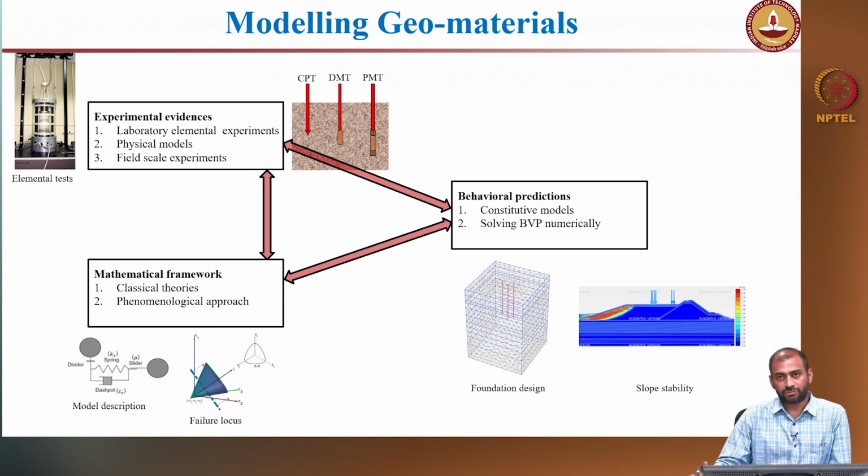Additionally, we also do a lot of field scale studies, right. We use the cone penetrometer test, flat dilatometer test, and pressuremeter test in the field to understand the stress deformation response. All these experimental evidences are key before developing any constitutive model, because this gives you a clear picture of how the soil behaves under complex stress paths and complex environments. Already the soil or a geomaterial is extremely complex. We will discuss why it is complex in the later slides, but it is complex.